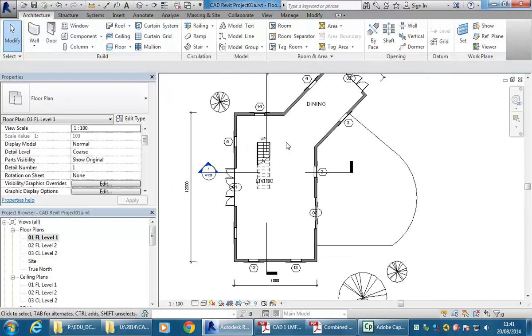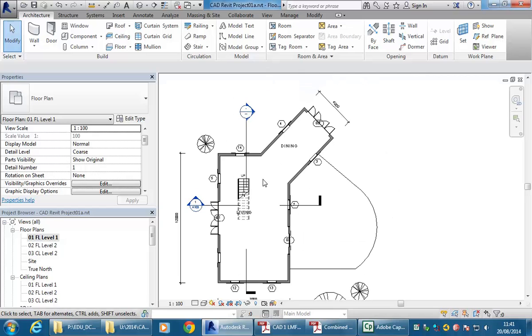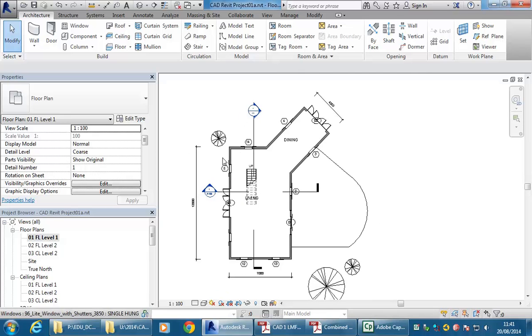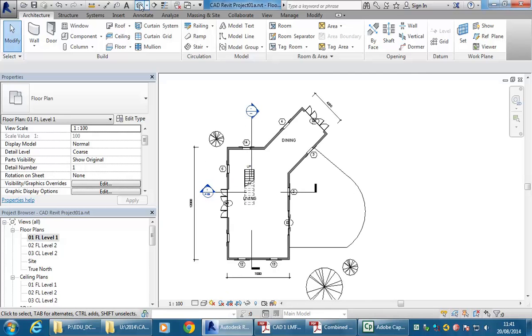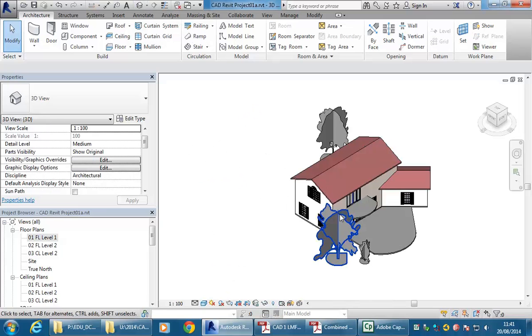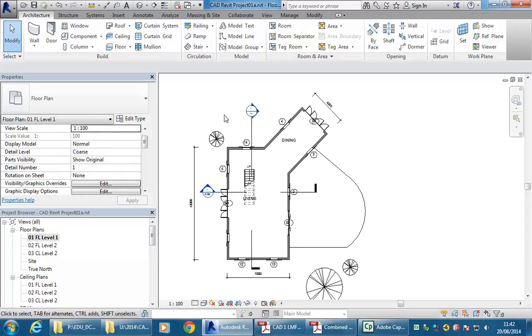Okay, so then how do we see that stair? Remember, if you can't see from the outside, looking in the 3D view, obviously we can't see that stair because it's inside the building. So remember, if you can't see things from the outside, you've always got your section views to see inside. And so here both of my section views are going to pick up that stair. And if you don't have sections that do show you what you want, just make extra section views.